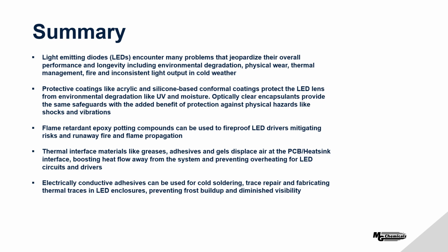Now to summarize. Light-emitting diodes, or LEDs, encounter many problems that jeopardize their overall performance and longevity, including environmental degradation, physical wear, thermal management, fire, and inconsistent light output in cold weather. Protective coatings like acrylic and silicone-based conformal coatings protect the LED lens from environmental degradation, like UV and moisture. Optically clear encapsulants provide the same safeguards with the added benefit of protection against physical hazards like shocks and vibrations. And in this presentation, we introduced both an epoxy and a silicone option.